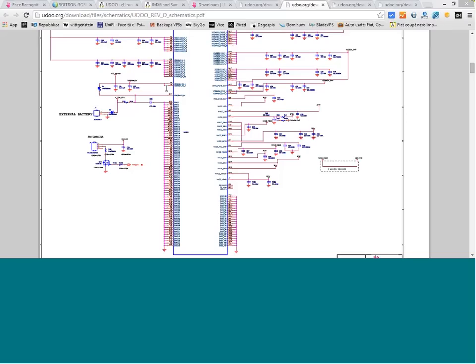If you use it as an Arduino pin, it will automatically be used as an Arduino pin. This means you should be careful not to trigger the same pin with the IMX6 and Arduino at the same time, especially setting one as output and the other as input with different voltages.